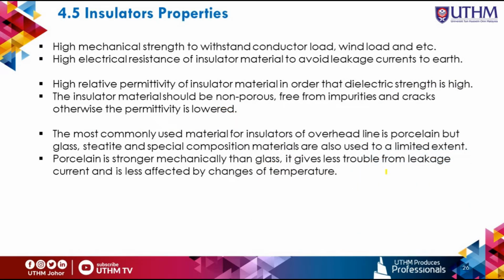So in general, the insulators should have the following desirable properties. The first one is insulators must have high mechanical strength to withstand the conductor loads, wind loads, and so on. Second, insulators must have high electrical resistance of insulator material in order to avoid leakage currents to the earth.